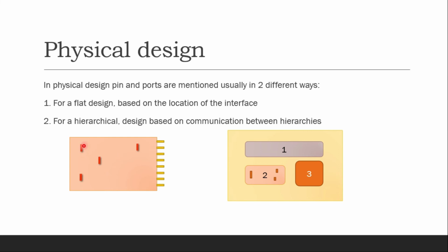And all the other interfaces that we provide to the upper hierarchy, maybe we call these ports. These are ports because they are given to the upper hierarchy in the middle of the design, whereas these are provided at the boundary of the design. But this need not be true always. This is not that standard, but it is also used. But more standard is this.